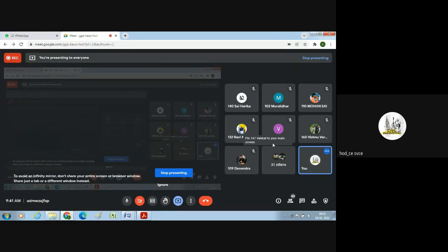Before we operate the instrument, we should level the instrument and locate the centering point. Centering and leveling is a must. Only then do we locate each and every station by placing the leveling staff. After placing the leveling staff, you direct the telescope and note down the readings shown. When you direct at your leveling staff, your telescope should be horizontal.